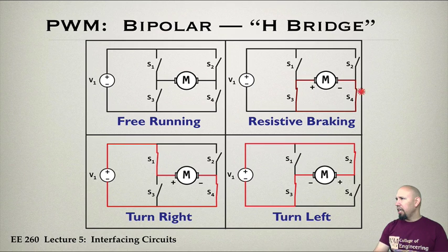Basically, here, the motor itself has resistance in it. It has an electromagnet, but because it has long wire that's coiled up to make an electromagnet, it has resistance, and this resistance, when it's in this configuration, basically takes energy. In other words, when the motor's spinning, it has kinetic energy, and when you hook in a resistor like this, the resistance in this loop is enough to dissipate energy